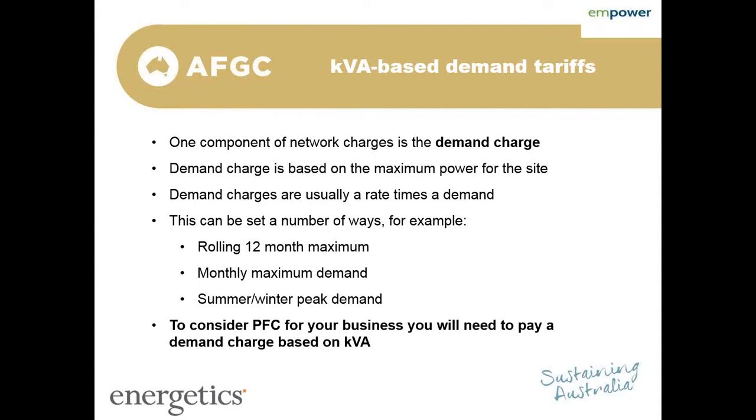And then another common structure is to have a summer or peak demand period. So typically it's a couple of hours on hot days. Your distributor will give you a heads up as to when that is, and then your demand during that period will set it for the rest of the year. So it's kind of irrelevant what you're doing the rest of the year, it just really matters in those few hours.